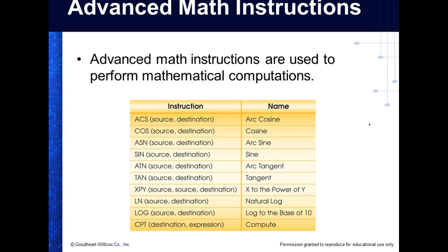And we can't count them every minute, so what we do is put a lot of stripes on the thing, and we might count it over a second, but we might need 30 pulses over a second. So these encoders have got what? A lot of slots in them. And we're talking about trying to control the speed of a motor that's running at 1,800 revolutions per minute, and I'm trying to bring that into a counter that runs off the software.